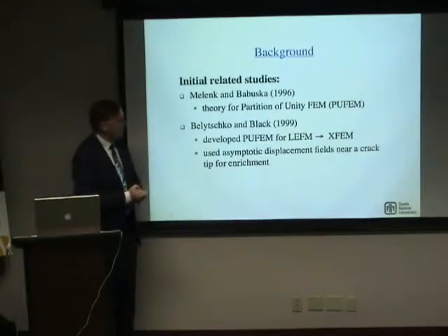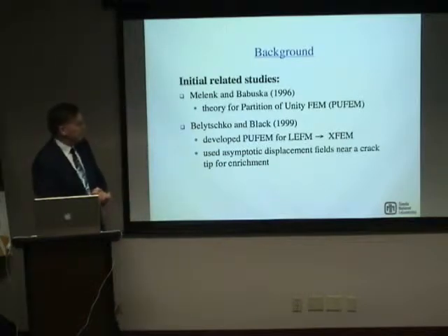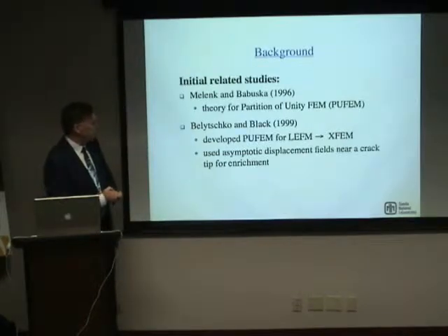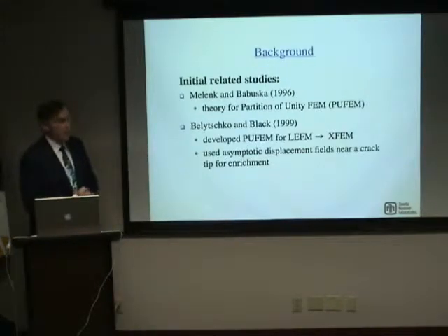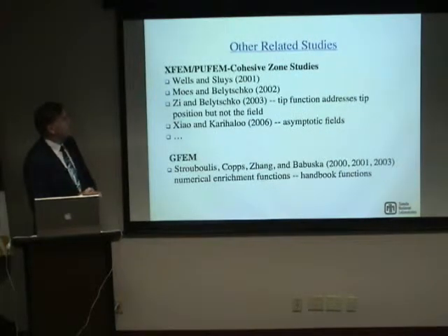And it's that term, extended finite element method, that's been referred to the most in the context of fracture. They use asymptotic displacement fields near a crack tip for enrichment. And as Professor Ganem just mentioned, that does have a singularity in it when you're looking at the stress.